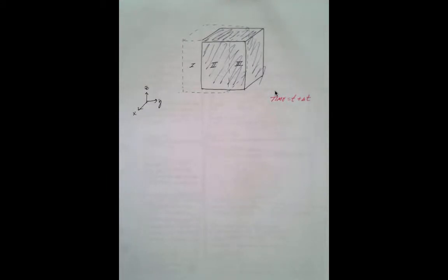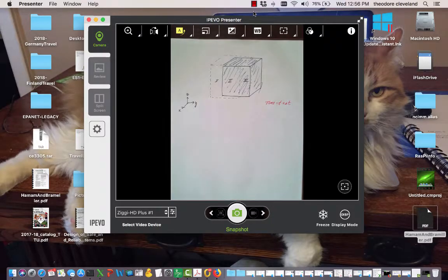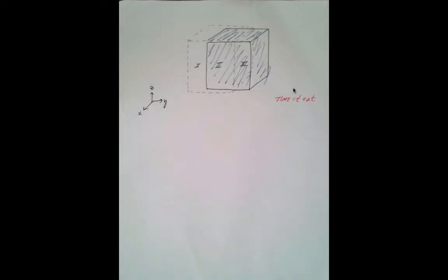So the next part of our analysis is going to be to examine these three zones and write them in integral form. So let's examine now the extensive property, capital B. In this case it's actually mass, but we'll use the letter B. And we want to use the definition of the derivative, which is the limit of a difference quotient, and that's going to provide us a guide.